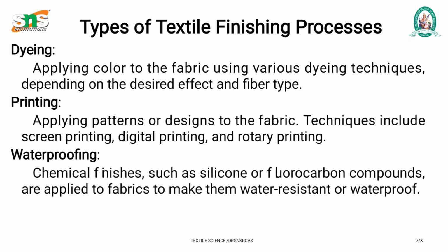Next, dyeing. Applying color to a fabric using various dyeing techniques depending on the desired effect and fiber type. Next, printing. Application of patterns or designs to the fabric. Techniques used include screen printing, digital printing and rotary printing. Next, waterproofing. Chemical finishes such as silicone or fluorocarbon compounds are applied to fabrics to make them water resistant or waterproof.